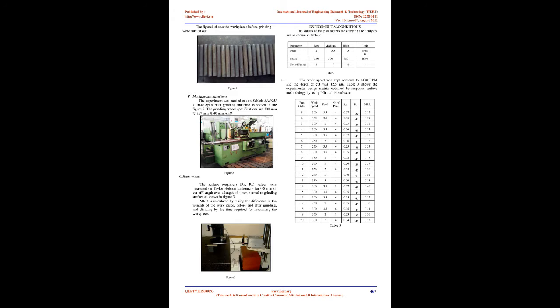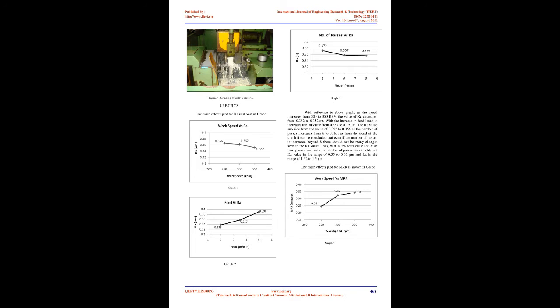3. Residual stresses remain in an object even when the external forces and loading are removed. In many cases, residual stresses result in significant plastic deformation, leading towards the distortion of an object. In others, they are the cause of fracture, crack propagation, and fatigue. When the residual stress on the surface exceeds the ultimate strength of the workpiece, there will be cracks and microcracks.